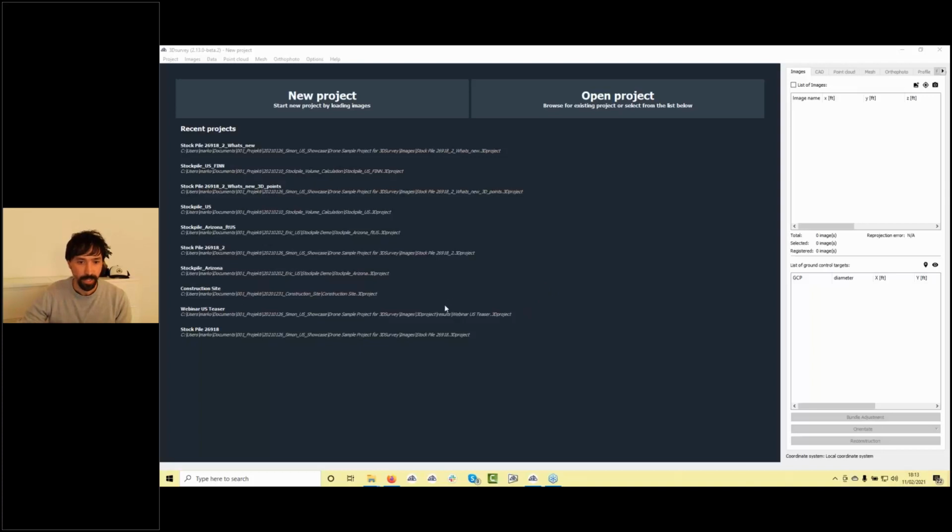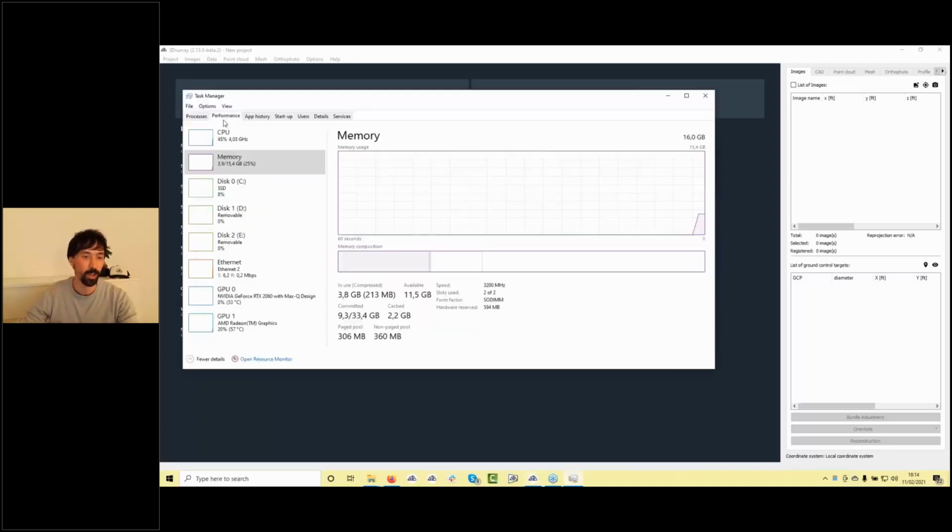Okay. Are there limitations for point clouds? What are the limitations? It depends on how much memory you have. When you load in the point clouds, you can easily load in about 200 million points. The memory is important here. If you have 128 gigabytes of memory, just go on. Okay, the hardware is the limitation.